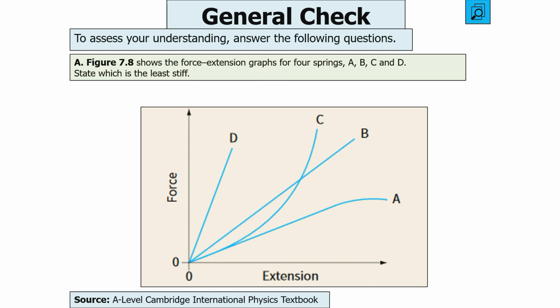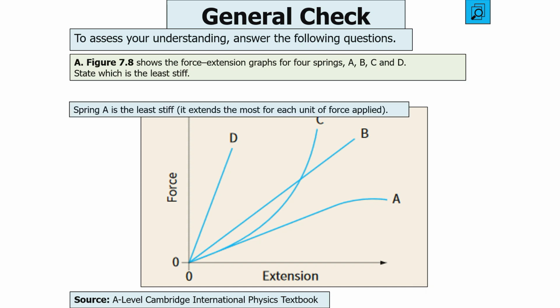State which spring is the least stiff. Pause the video now, then unpause the video when you want to go through your answer. The answer is spring A, as it extends the most for each unit of force applied.